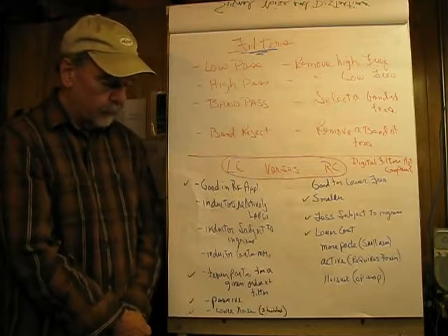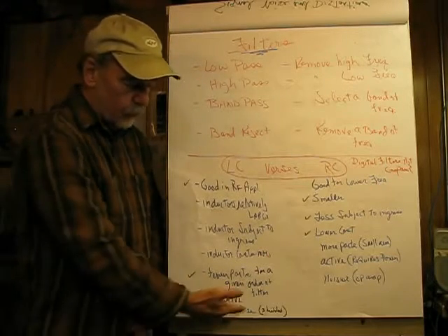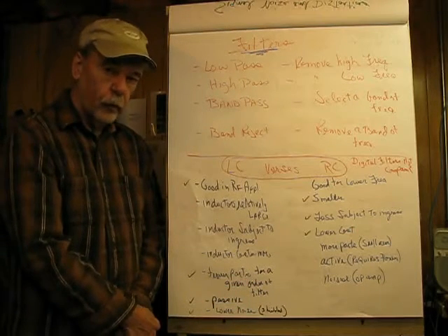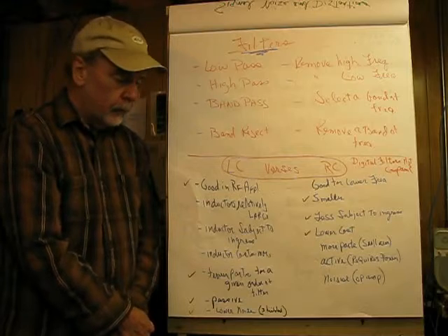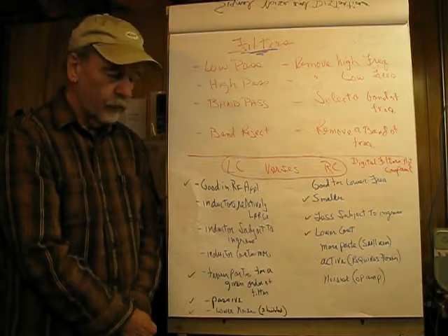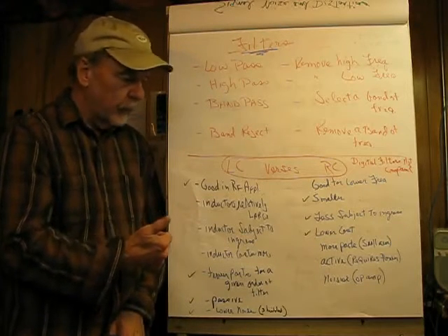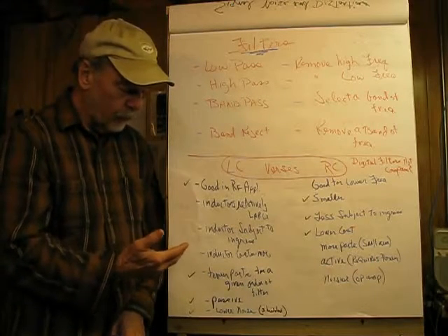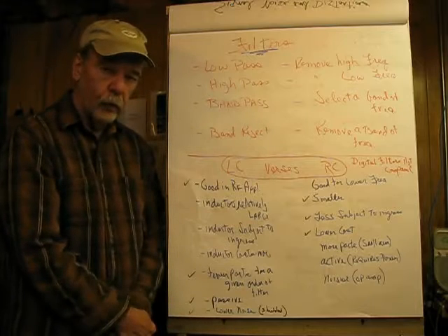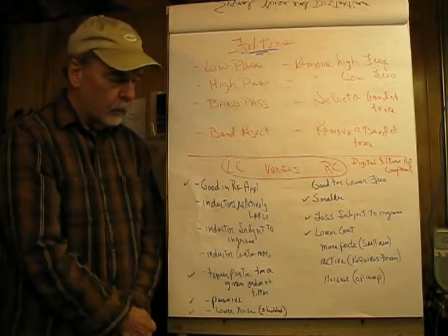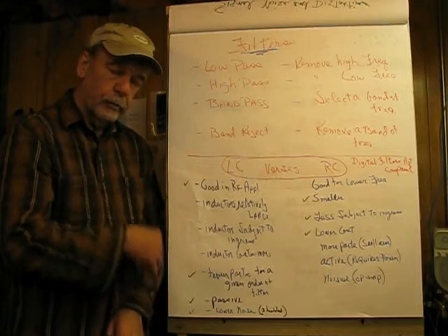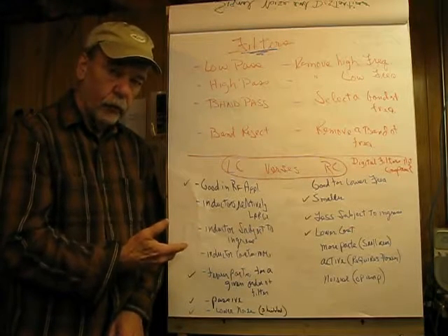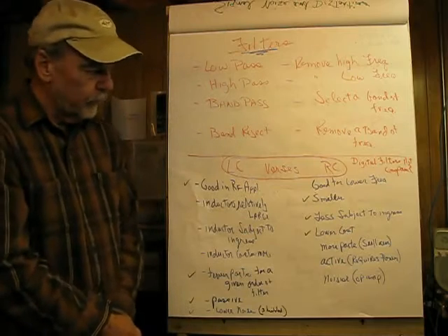Now we have to be a little bit careful when I say that, because this is shielded, and the noise I'm talking about is Johnson noise, white noise, and what that's proportional to is the bandwidth of the circuit, the temperature, and Boltzmann's constant. So the only noise that's going to be introduced by an inductor is its winding resistance. Inductors, meaning the inductive component, or capacitors, do not introduce Johnson noise.